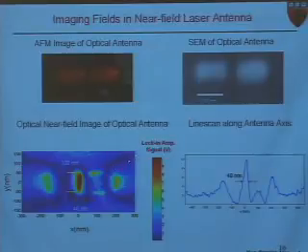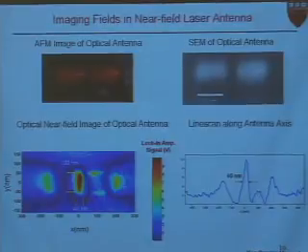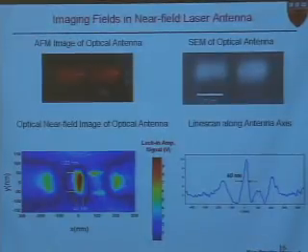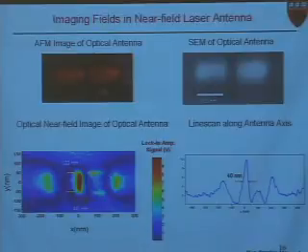And that's the output of that lock-in amplifier as a function of position of the tip. And I'm very excited when we got this result, because what we can see is that inside the gap of the antenna, we have a spot that's 40 nanometers across by 100 nanometers. And I should point out that this laser is operating at a free space wavelength of 830 nanometers.